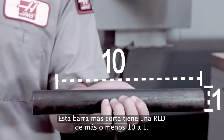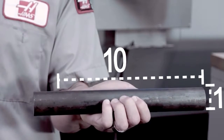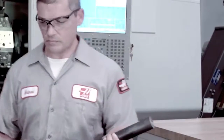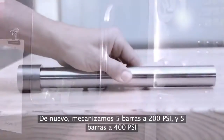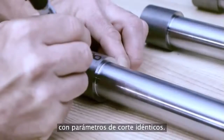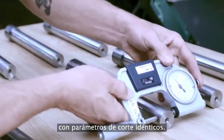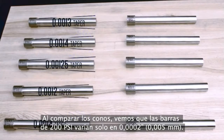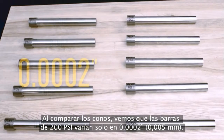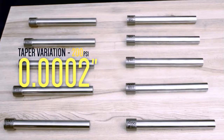This shorter shaft has a supported L to D of about 10:1. Again, we cut 5 pieces at 200 psi and 5 other pieces at 400 psi using identical cutting parameters. We check diameters and find our taper values. Comparing the taper values, we find the 200 psi shafts vary by only 2 tenths.